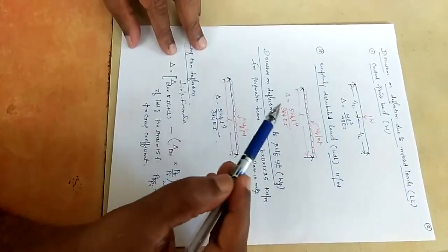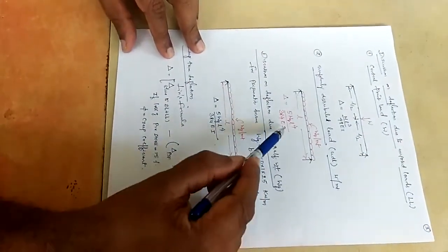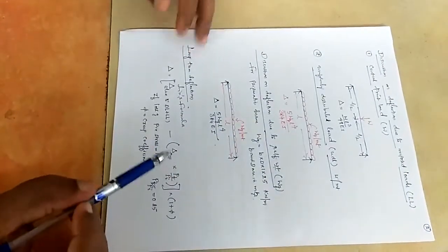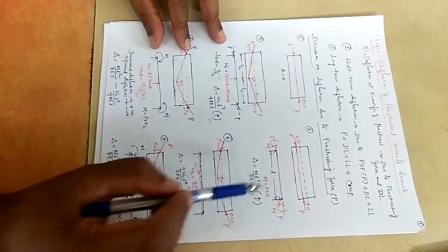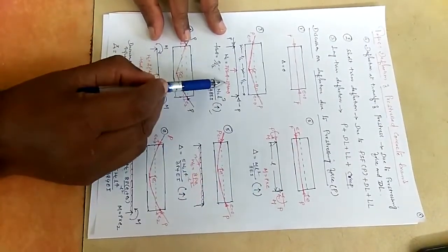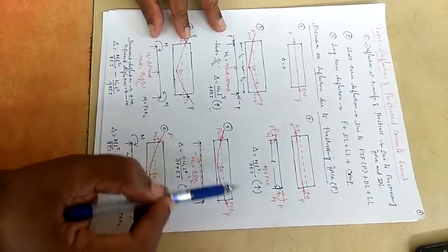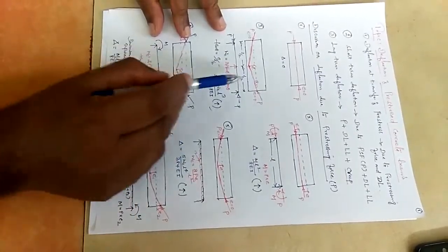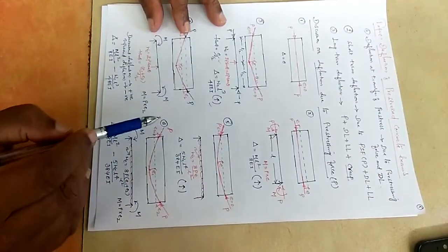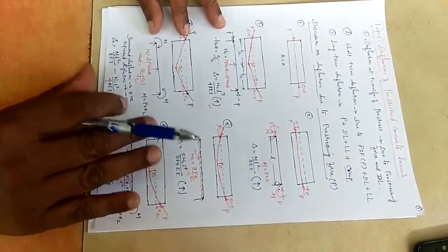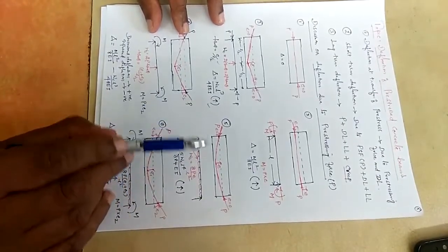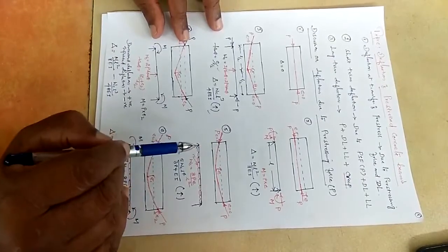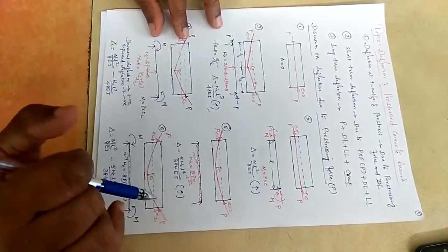It may be a rectangular, L section, I section. Okay. Moment of inertia. Then if you see this formula, here P is important, M is P into E, here 2P sine theta. Prestressing force is important, that also influences deflection, and eccentricity of the cable will influence deflection. Just by referring the formula you can answer that one. There will be always a question, what are the factors influencing or effects on the deflection. Some 5-6 factors you have to write.